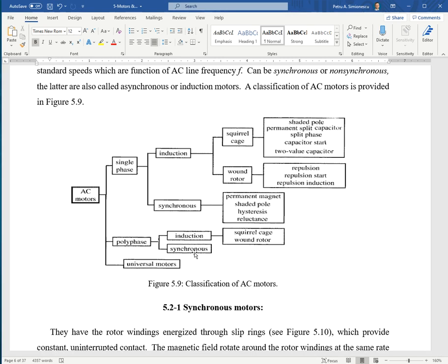But for the polyphase, you need to bring them to the synchronous speed before you can use them. And being high efficiency, you see them used in large applications, like large pumps for utility works, or to circulate air through tunnels, on subways, or in mines.